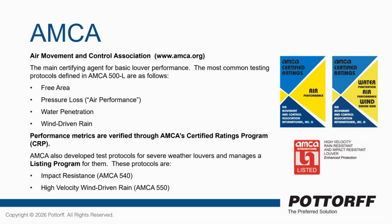That 500L lays out the base testing for four key performance features of a louver: the free area, the pressure loss, or what they call air performance, the water penetration, which we've been discussing as water moving down a building, and then wind-driven rain.